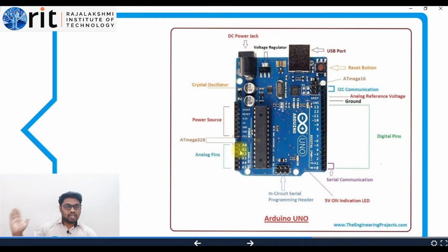If you are using any other microcontroller, you should have a separate A to D converter for processing an analog sensor. So here it is dedicatedly given, A0 to A5, that is totally 6 pins for analog sensors, so you can directly interface your analog sensor to the board.